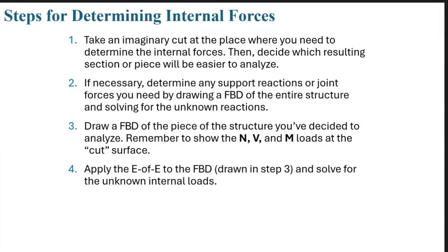of Mc = 0. If it is three-dimensional, we need 6 equations. Okay, after that, draw a free body diagram of one side of the imaginary cut. Which side? You should be smart in choosing the part that has the minimum external forces, or is simpler, not complex, because it is easier to work with. Then write the equilibrium equations for that part and find the shear force, axial force, and bending moment.